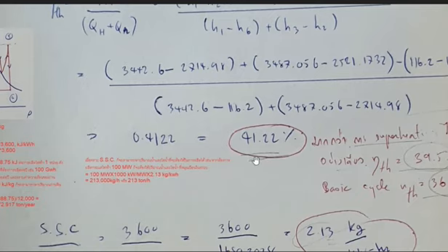And for the superheating and reheating cycle, we get 41.22%, which is better. And I also did an example for just the basic cycle, no superheating, no reheating. We will get a thermal efficiency of about 36.8%. So it is proof to us that with superheating and reheating, we can increase the thermal efficiency.